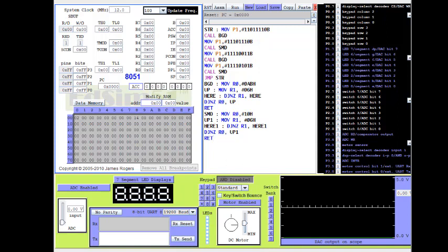In this particular practical we'll be using the LEDs as the signal lights. These LEDs, which I'm marking, are 8 LEDs provided, arranged in such a way that the top one is the red one, then the second one is the yellow, then green, then red, then yellow, then green. So the first 6 LEDs can be used as the signal lights. We can assume that the first 3, red, yellow and green, can be used for the north-south traffic, and the next red, yellow and green can be used for the east-west traffic.